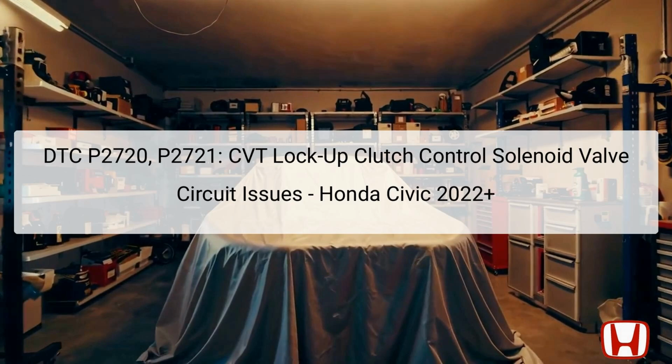The Diagnostic Trouble Codes DTC P2720 and P2721 relate to malfunctions within the continuously variable transmission CVT lock-up clutch control solenoid valve circuit in the Honda Civic models from 2022 and onwards. The P2720 code indicates that the transmission control module, TCM, cannot detect the proper current flow to the CVT lock-up clutch control solenoid valve over a specified duration when the valve is commanded to engage.